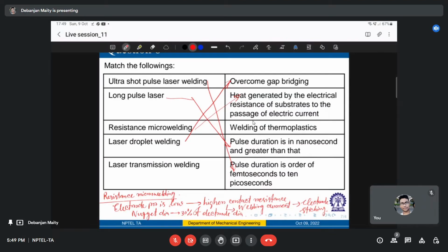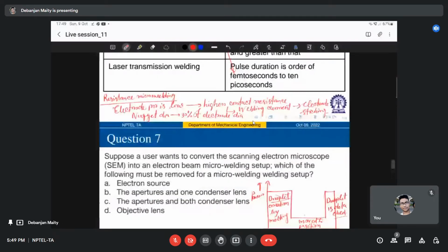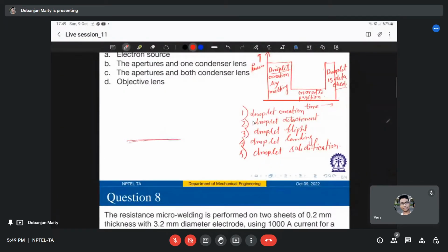And unlike standard welding, where the energy is applied at the surface of the materials, transmission welding aims to apply the energy in between the two plastic pieces at their interface. So, if you try to figure out a schematic, there will be two plastic pieces.